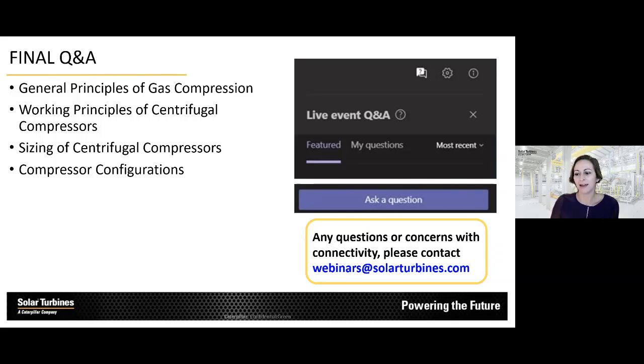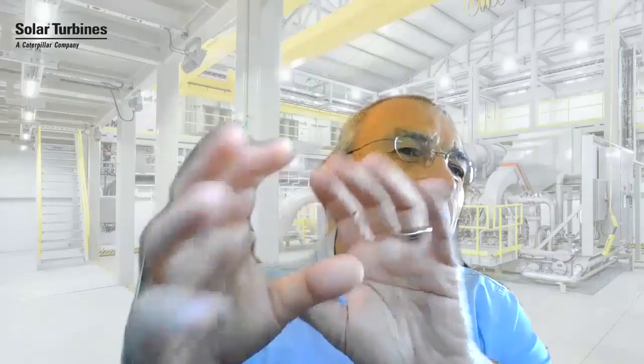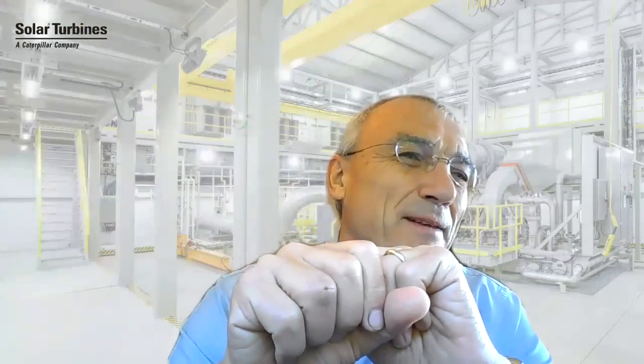Is the Solar compressor rotor considered flexible or rigid, since it's only low speed balanced? It operates above the first critical and below the third critical. So in that sense, it bends. But obviously, I'm a bit hesitant to be more clear than that, because essentially where in that range you operate depends also on things like bearing stiffness.